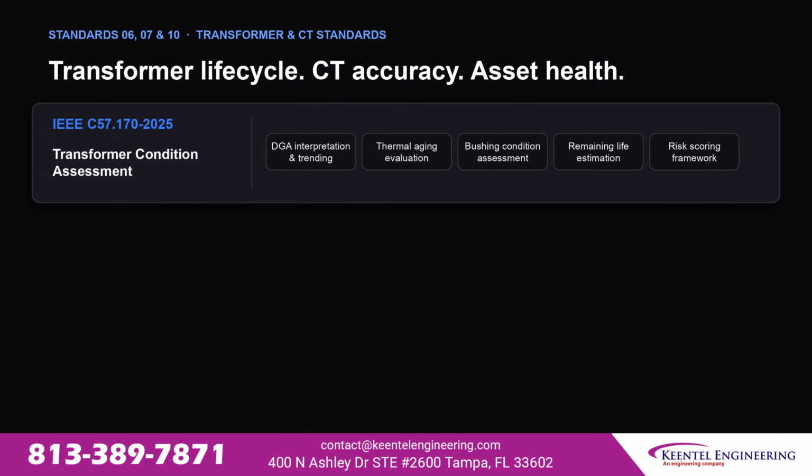IEEE C57.170-2025 formalizes condition assessment for liquid immersed power transformers, covering dissolved gas analysis, thermal aging evaluation, bushing condition assessment, insulation life modeling, and risk scoring. The shift is from time-based maintenance schedules to data-driven asset management. That reduces both risk and unnecessary cost.